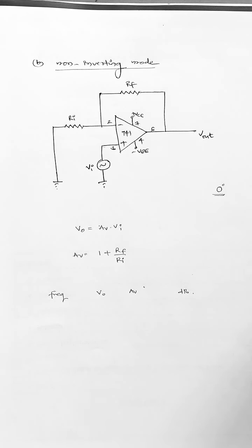Now we will connect these two circuits on the breadboard and we will verify the output waveforms. Try with different values of frequencies, note down the output voltage, then calculate the gain and the gain in decibels, and try to draw the frequency response on semi-log paper.